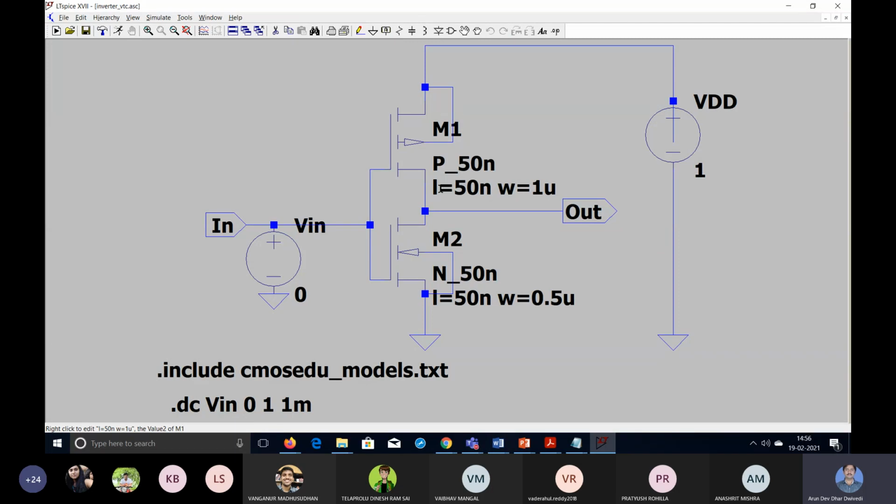So this is another extra point, and another point is that we are making here one input port, and that point is the output port. Though it is not required to show the port, how to create a port is given. If it is not there, then no problem, this voltage is already connected. But during the creation of the symbol, we will remove these voltage sources, this ground, and this voltage source also. Only we will make an input port, a VDD port here, and a digital ground port here, and one input port at input and one output port at output. Then we will create a symbol to further use this inverter circuit in any other higher level of design. So that is why input and output ports must be required: input port, output port, VDD port, supply voltage port, and the ground port. That will be done next.